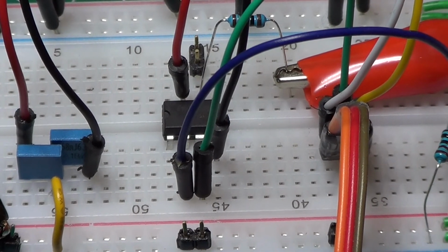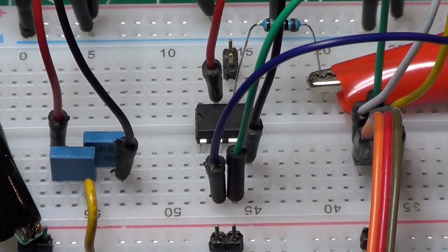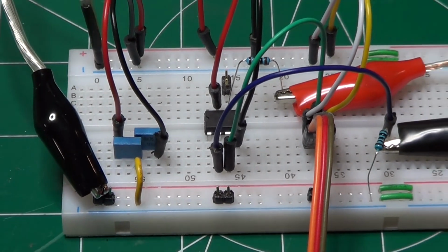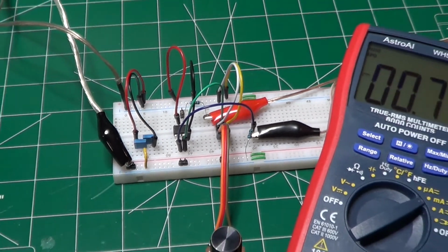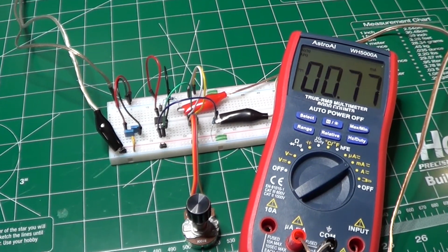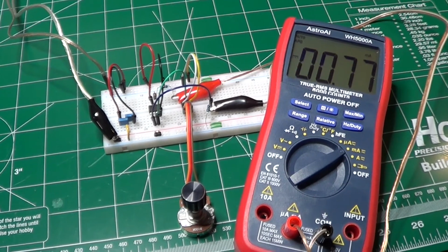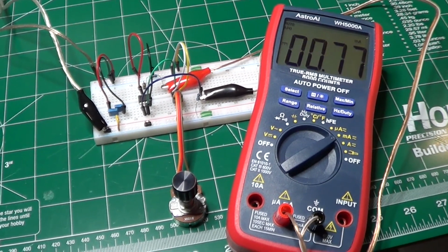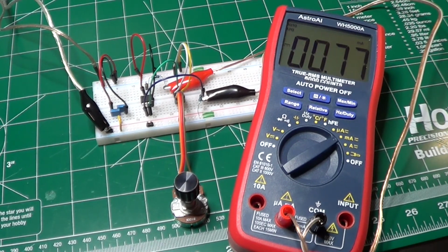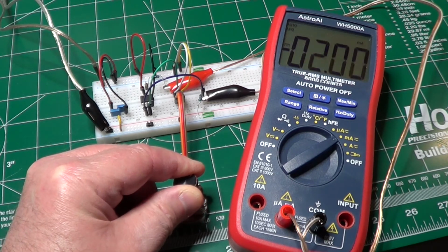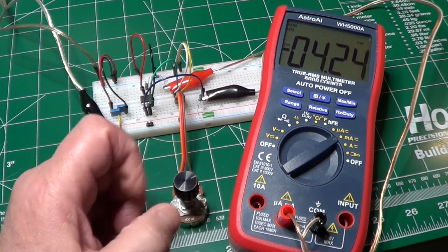Here is the circuit mounted on a breadboard. You can easily see the load mounted on the output, which is pin 6, which is also connected to the alligator clip that goes to the ammeter. The ammeter is currently showing a current of 0.77 mA. And now you can see how, acting on the potentiometer, I can change the value of the current, and I can have either a negative or a positive value of it, depending on the sign of the reference voltage alone.